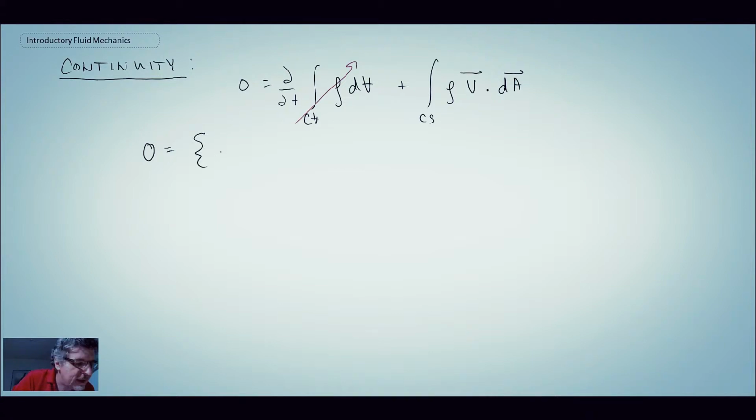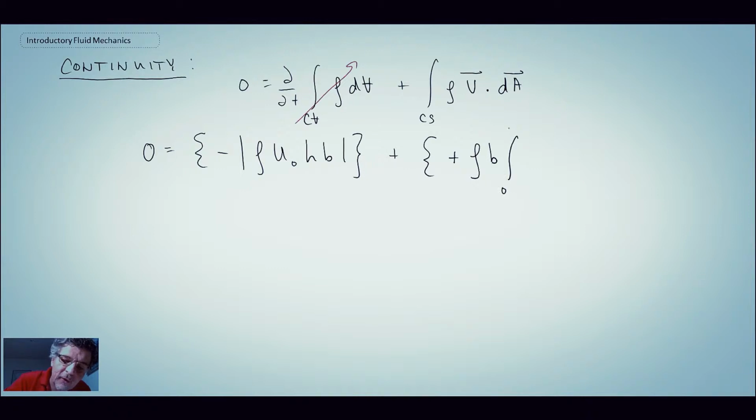And so using the technique that we have been using throughout this course, whenever we look at mass flux coming in through surface 1, it would be a negative due to the arrangement between the velocity vector and the area vector for that surface. And then for the mass flux leaving through 3 on the right-hand side, that would be a positive, but it is an integral from 0 to delta. And delta, by the way, is the boundary layer thickness. And it was the velocity profile u dy. So he performed an integral there.